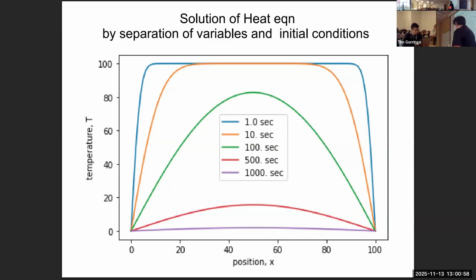A moment after you've dropped it in, say 1 second after you've dropped it in, heat is starting to flow out. Energy is flowing out, but really only the far left of the rod and the far right of the rod know it's in contact with something that's cold. And the flow of heat, the flow of energy, and the change in temperature is at the far left and far right hand ends of the rod.